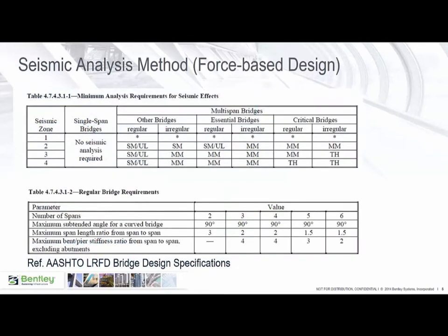Seismic analysis method, force-based design. AASHTO LRFD provides guidelines for deciding which force-based design method should be used. The decision is based on whether the structure is regular or irregular and the seismic zone indicating the severity of the seismic ground motion.